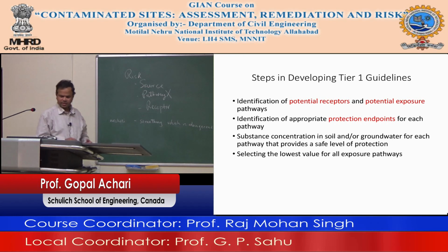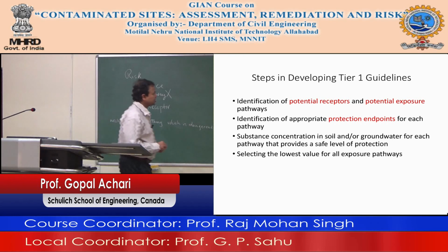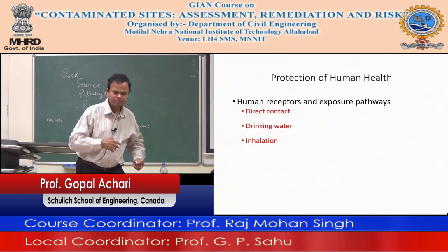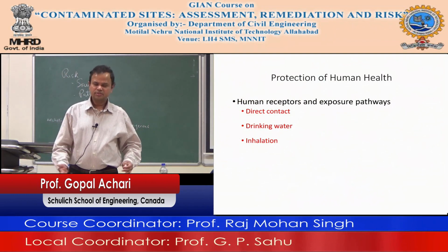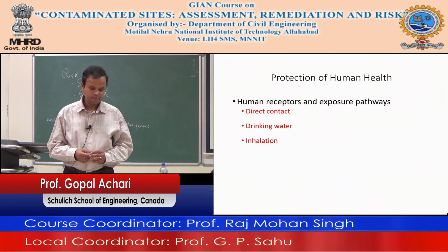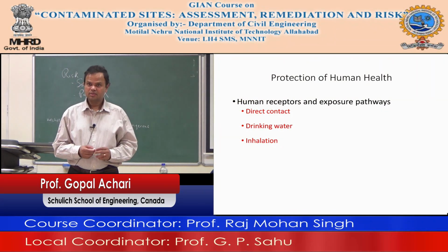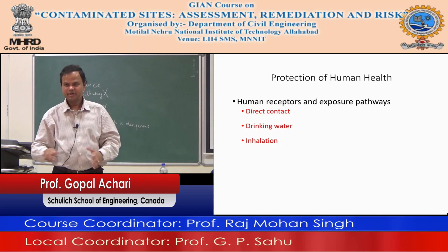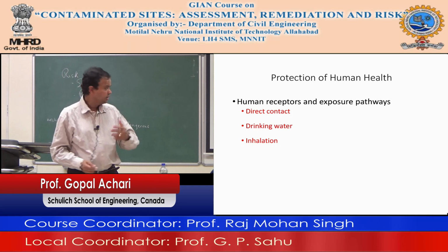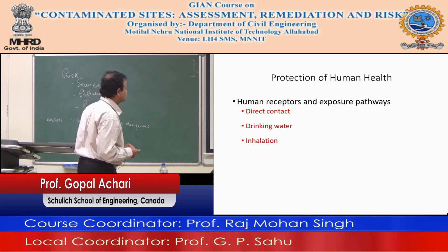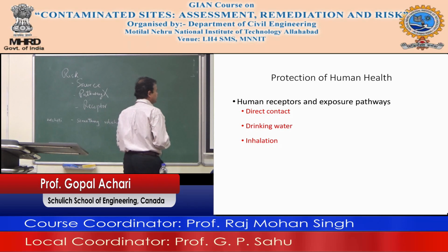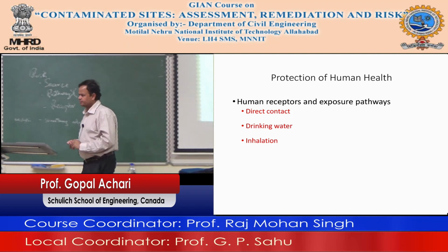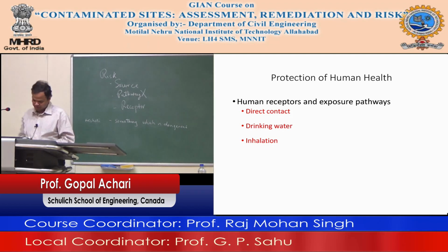Protection of human health. You have to look at things like dermal contact, inhalation of soil particles. Okay, so you also have to think about the risk to the workers. You take out a site, now it's all over the place, right? You know, it is buried and all that, but now you have taken it out, it's in the air. You'll have inhalation of soil particles, and then drinking water, showering, bathing, inhalation, volatiles being released into the soil, groundwater migrating into living and workspaces.